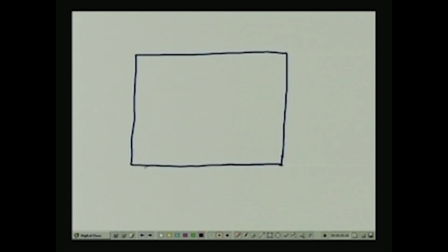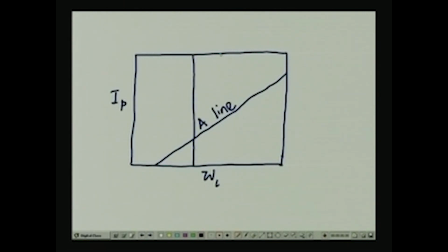And there what I said is that you have got an A line. So, this one is the A line, and what we are doing is plotting the plasticity index against the liquid limit, and I said that in case of the IS code, you have got two vertical lines really at WL of 35% and WL of 50%.